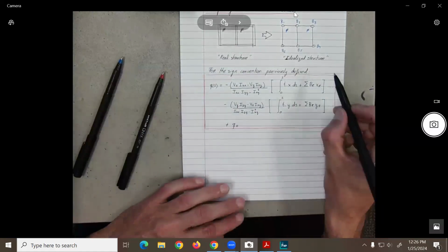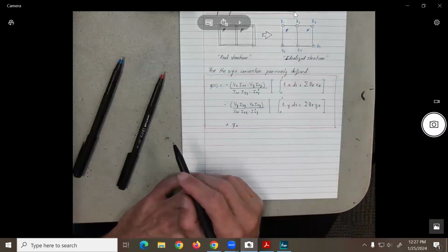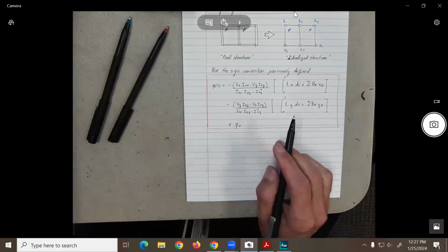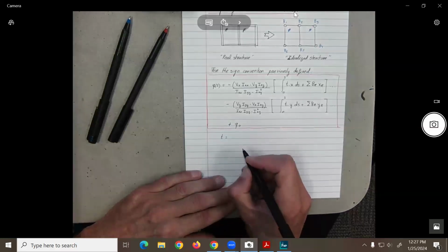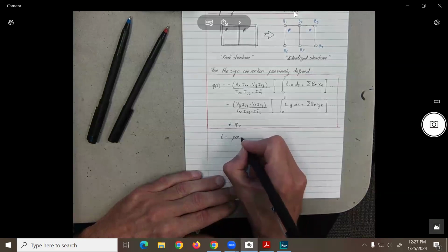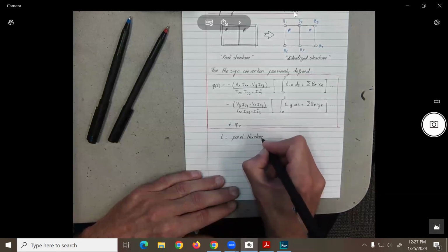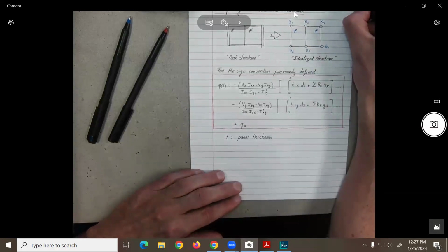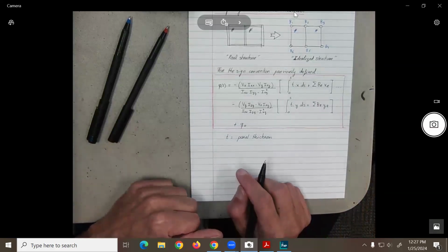Okay, so what is r? r is the number of booms, no? It's like an index. All right, so let's put here some legends. What is t? t will be the panel or plate thickness. In the British books, they call it actually web, but I mixed the notation.